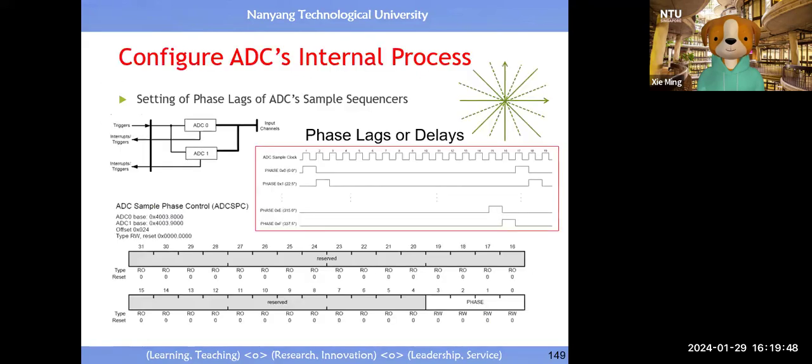So this is in case for your application you want to double the resolution. That means input is one sensor. Then you use these 2 quantization devices to do the conversion of a value coming from the same sensor, right? So when you do the sampling, if you make the offset 180 degrees, create this offset.